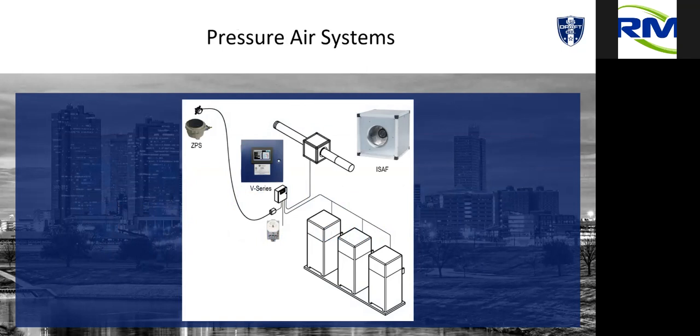It takes out the louvers, takes out the big dampers and drives, takes out direct vent, running multiple pipes to multiple boilers. This will actually just dump air from the outside, and it can be either dumped into the space, or can be manifold with drops to each appliance. As boilers come on and off, air gets taken out of that space. Our sensor realizes that, senses the pressure drop, modulates that fan up to put air right back into the space. We're just trying to maintain a neutral. It works really well. It's very cost effective versus large louvers and dampers.